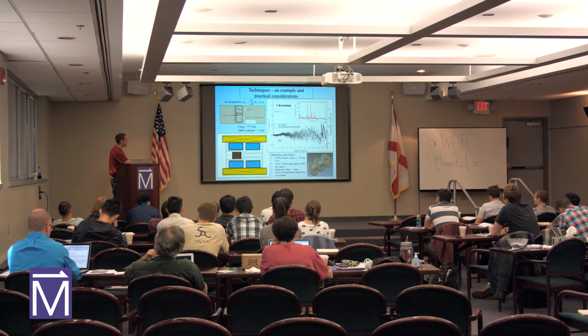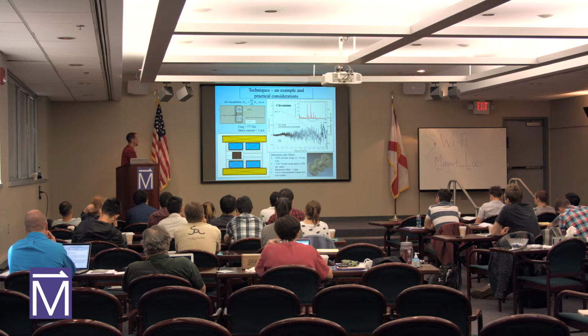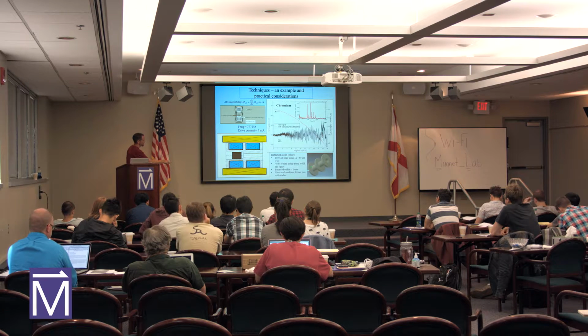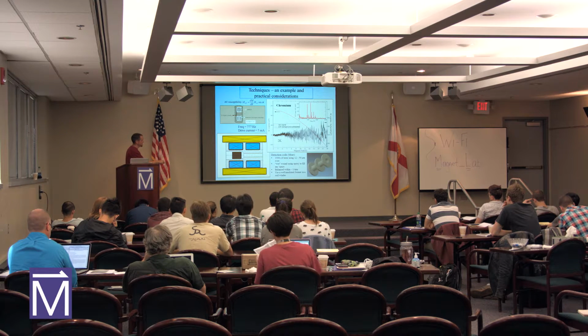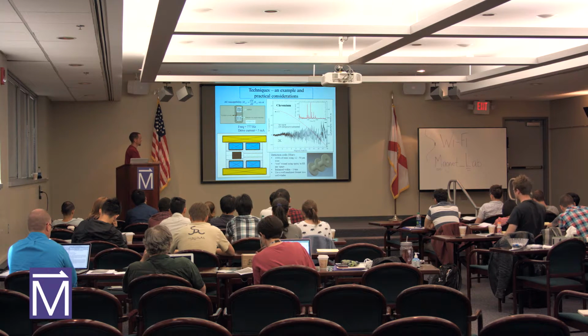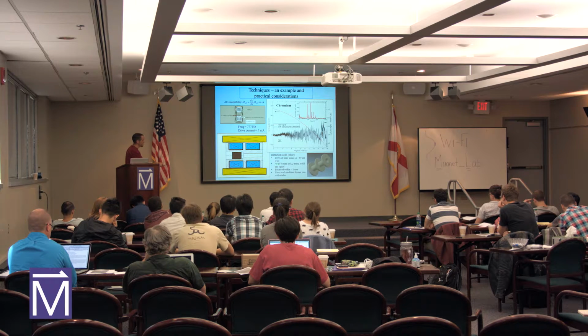And inside the excitation coil, these orange spots, these blue spots, are the detection coils. These are wound on what we call a former. It's usually some piece of plastic, G10, something that's magnetically inert, that you can't see magnetically. And you'll find wire on these on both sides. It's usually thousands of turns of wire, and the diameter of the wire might be between 12 and 50 microns. When you get thousands of turns of wire on there, usually as you're doing it, you're wet winding it. You're putting epoxy between the turns to fill up space because you don't want the turns to vibrate.